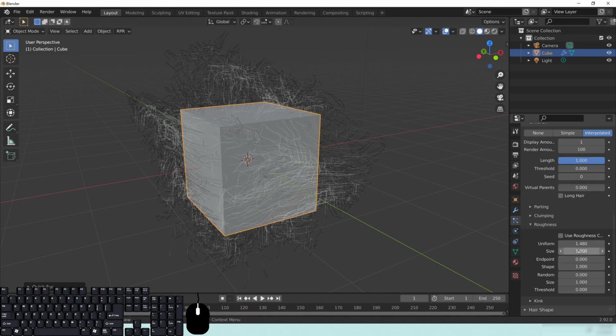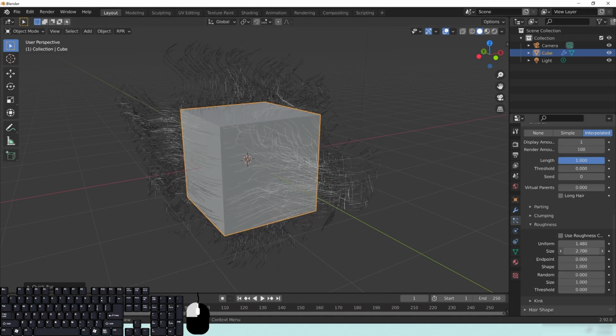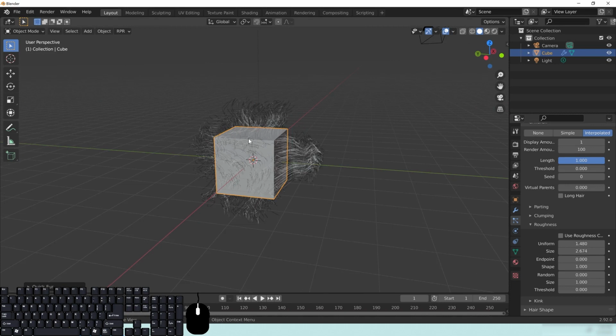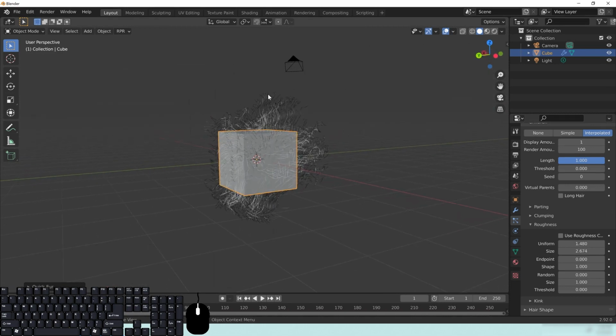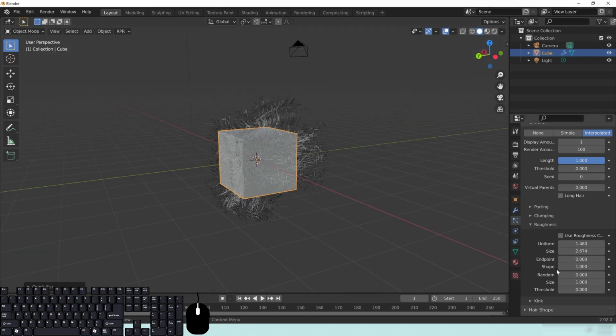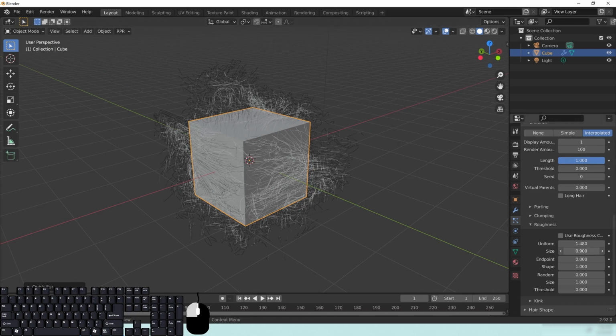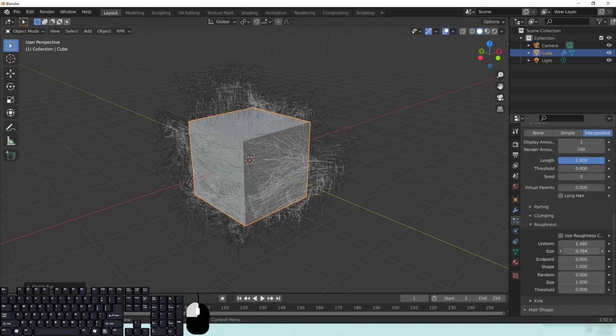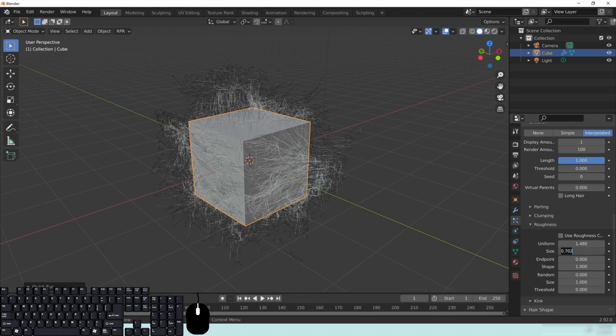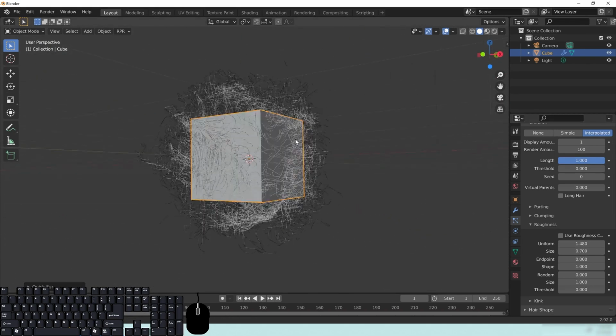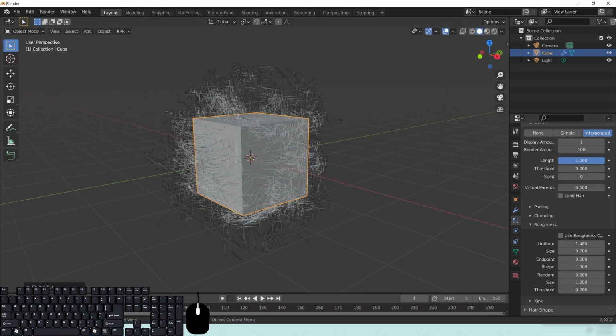And then also right here, the size. The larger you make the size, it's kind of like a noise shape. So the larger it is, the more you'll have these large pieces that are a bit longer, and then these other ones that are set like that. So what I actually want to do here is take this and bring it down a bit, because when we do our render, I don't want to see the edges really of this shape. So I'm going to pull the size down to about a 0.7. I'm just going to type in a 0.7 here. So something kind of like that.